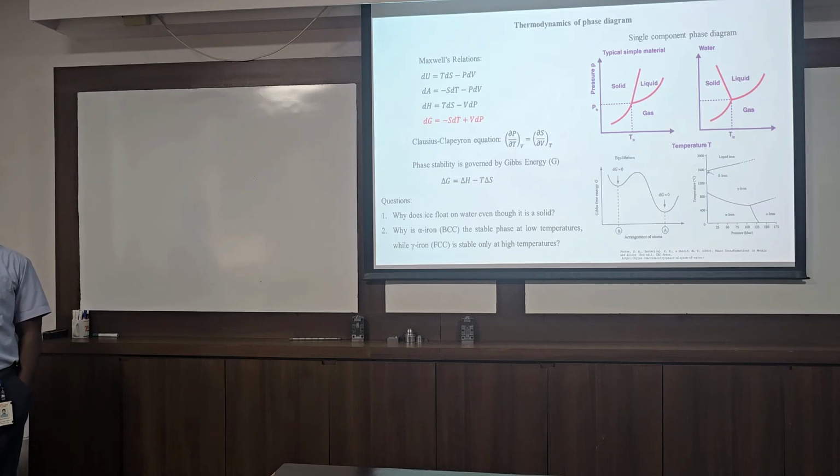You know what entropy is? That means the system will use this energy just to reshuffle itself into a different organization, meaning atomic arrangements. We cannot use this energy, we cannot extract it from the system. So what we have is the free energy. When we subtract this, whatever remaining energy is there can be used for the transformation. At phase transformation, some energy is required, and that energy is dictated by the difference in this energy. So Gibbs free energy is the main governing equation to construct the phase diagrams.